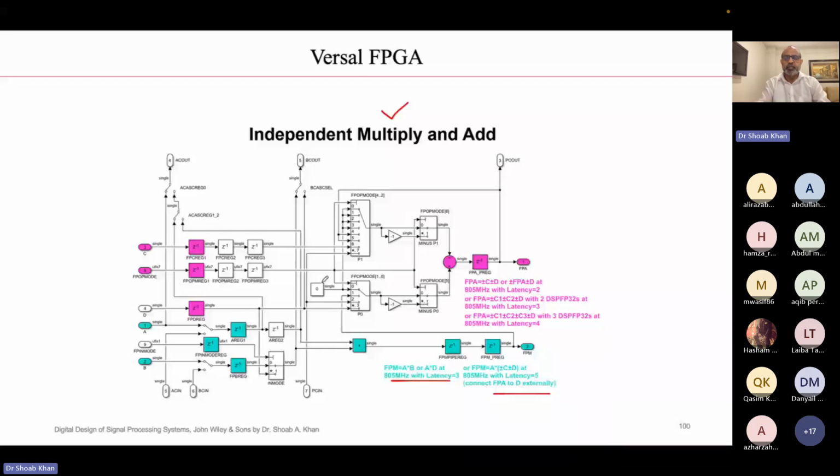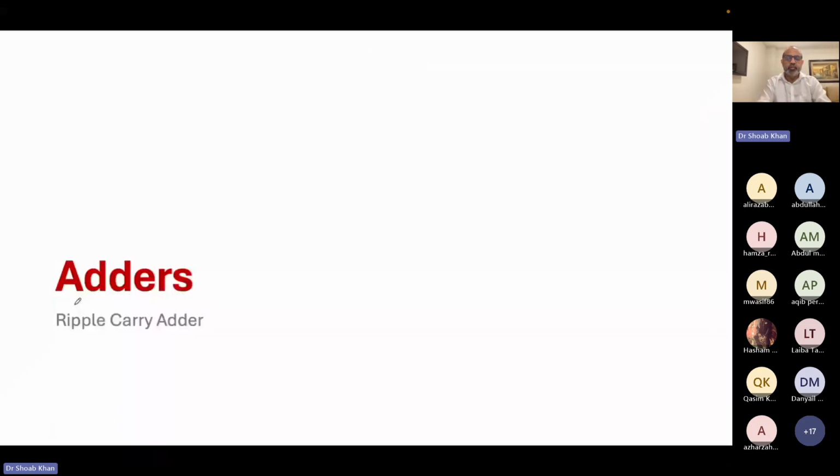They have these macros, they have actually developed the logic around it to give you the functionality of a floating point adder and multiplier. But if you intend to develop one of your own, here you have to explore the design space, the same design space. Are you willing to spend more area? Then obviously there will be an issue of routability that you will find out. Even just putting a 32-bit adder will have issues of routability, even if you're mapping them on FPGA. Power definitely is going to be an issue, that is, how fast you can add numbers.